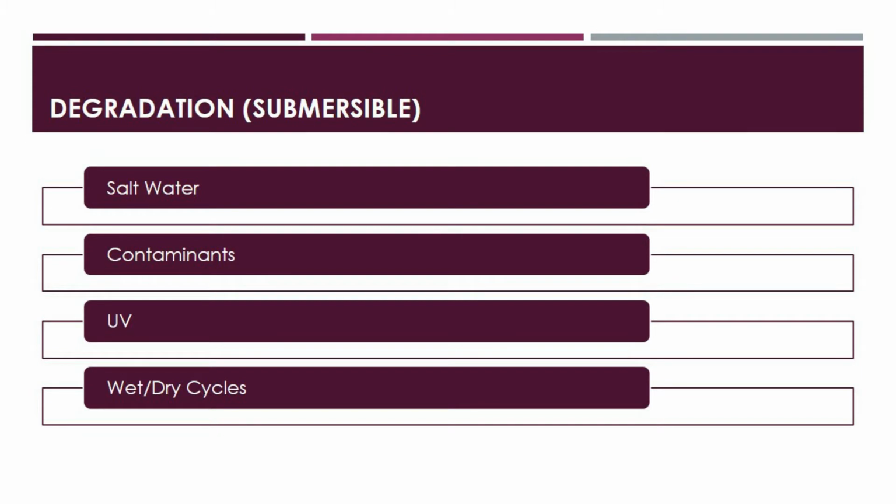After a number of operations, the electrical connections may actually deteriorate within the switchgear. Surface melting and erosion owing to heat stress, mechanical deterioration due to friction, and surface oxidization due to hostile conditions can all contribute to electrical contact degradation.